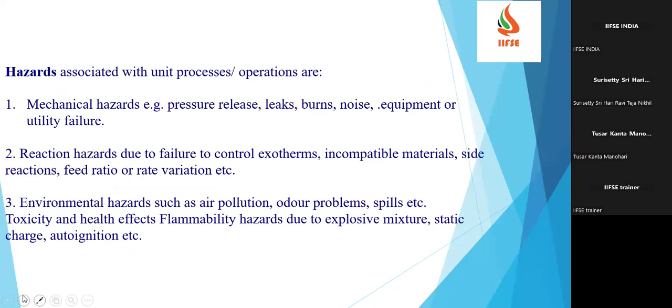Now the hazards associated with unit processes or operations. One is mechanical hazards: pressure release, leaks, burns, noise, equipment or utility failures. With respect to reaction hazards: failure to control exotherms, incompatible materials, side reactions, and feed ratio or rate variations.